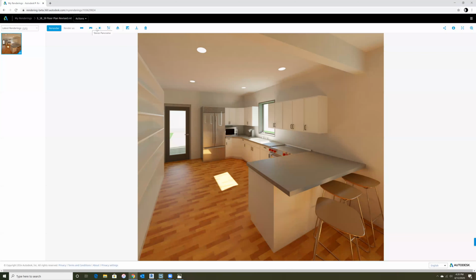So it's just a matter of playing with each of these settings. After you do that, it will require you to re-render it in the cloud. Re-rendering only takes about 5 or 10 minutes for it to be done. And usually sending a rendering to the cloud takes about an hour depending on how much detail is in it, but it's still faster than rendering inherently in Revit.